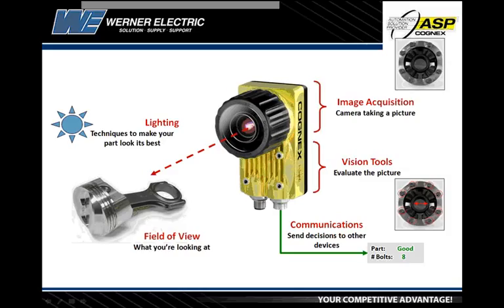When I do interactive training, that's a trick question that I like to ask: what's the most important optical component in your machine vision system? And the answer is your part, because we can engineer the light source, the optics, the camera resolution. These are all things that we can control, but we cannot control the optical variation in your product that we have to inspect. So that's where we need to focus all our efforts. What is the amount of variation of good product and the amount of variation of bad product, and where's that line?